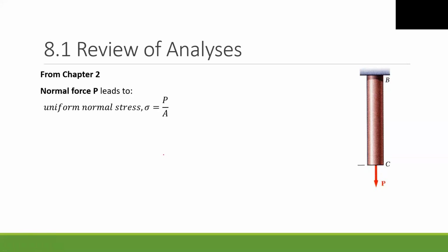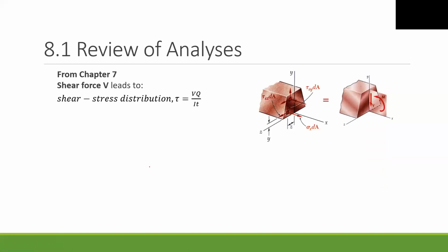Like this. Okay, maybe we can pass to the next slide. If we have a shear force, you remember from statics, shear force causes shear stress. How can we compute the shear stress? The formulation, maybe from chapter 7, you can figure out. Shear stress, which we represent as tau, as you remember from two slides before, is equal to V times Q divided by moment of inertia times t.